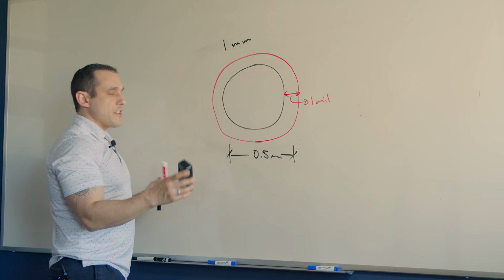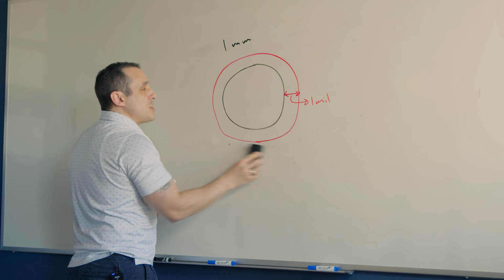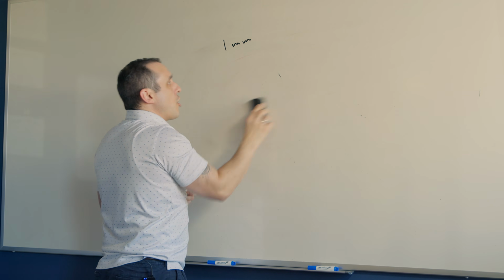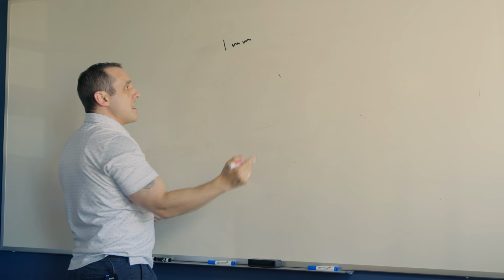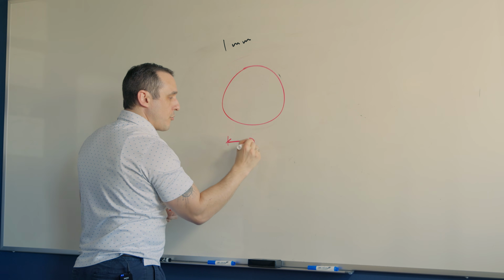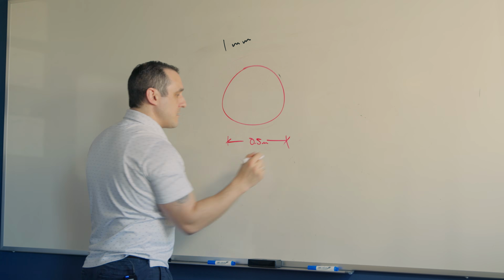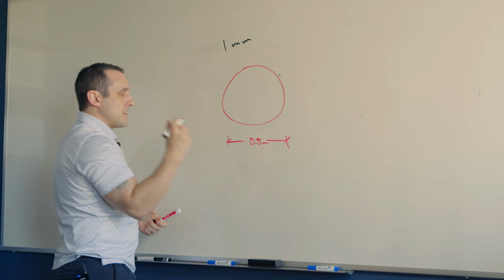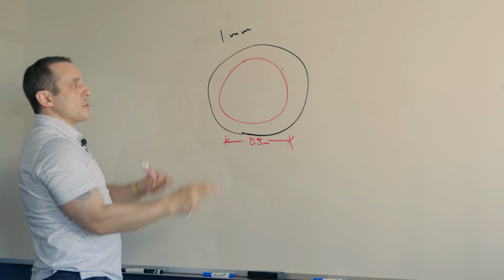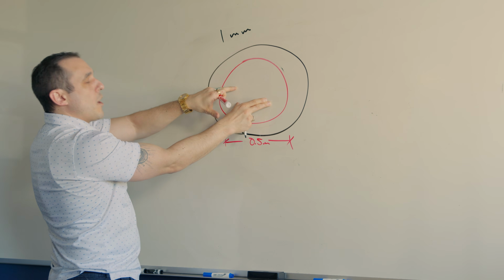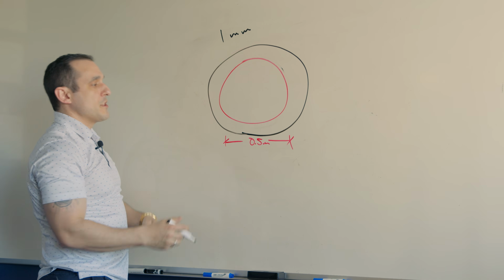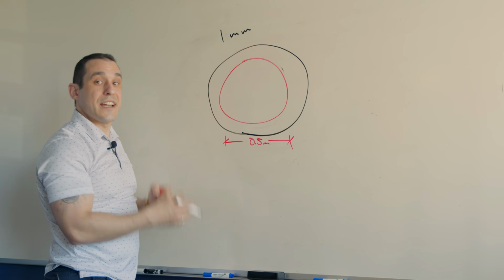mask defined pad. Now, the other way to define one of these pads is to actually use the size of the solder mask in order to set the size of that opening. So if we have a solder mask defined pad, instead what we do is define an opening of, in this case, 0.5 millimeters in diameter, and then we set the size of the copper to be anything larger than 0.5 millimeters. So now the size of the opening here is what defines the amount of exposed copper that the BGA will solder onto. And so this is called a solder mask defined pad, or an SMD pad.